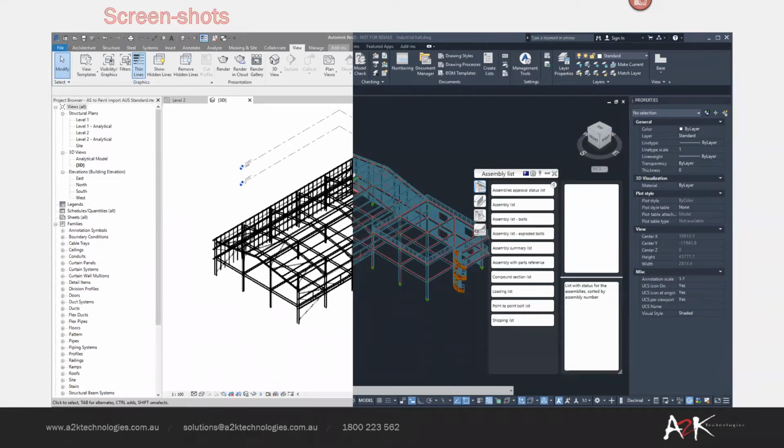I would focus on really just exporting those steel structural elements, but you can export your slabs and footings, etc. The resulting file is only a fraction of the size of the original Revit model, so it's very easy to exchange as an email attachment. It can then easily be imported into Advanced Steel, and it eliminates the need to recreate any of that existing information. That same information will go through and you'll almost have that one source of truth.